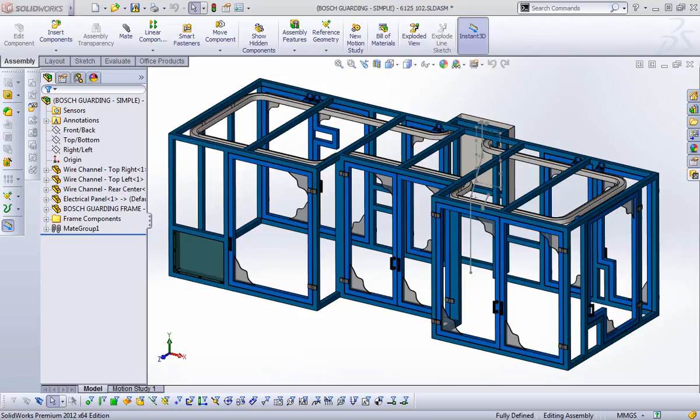In the weldments section, really the only new thing is how you create sub-weldments. If you save a sub-weldment body to a new part, then the cut list properties from the parent item get propagated to the sub-weldments. So actually, since I have a weldment here, I'll show you.